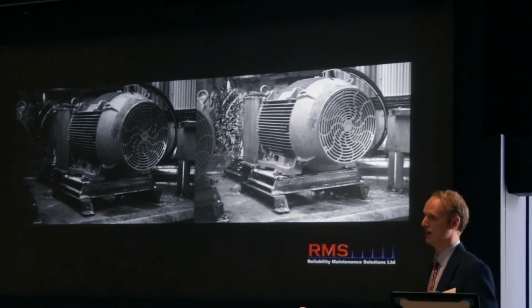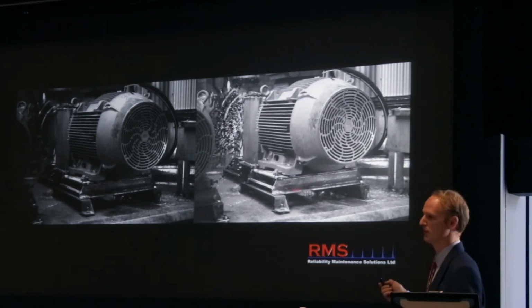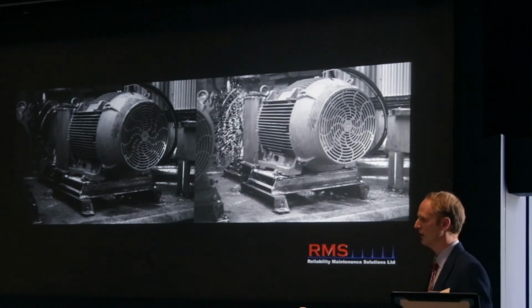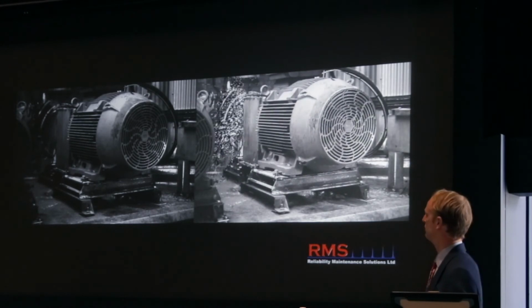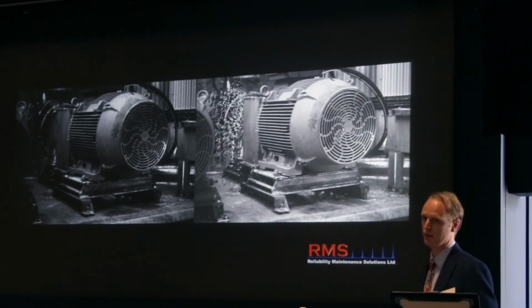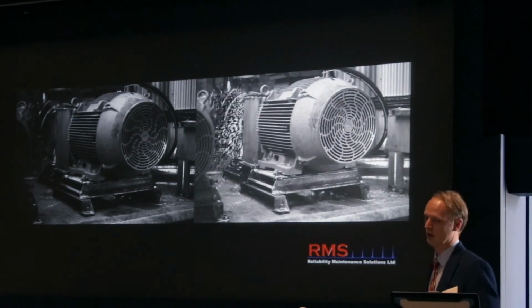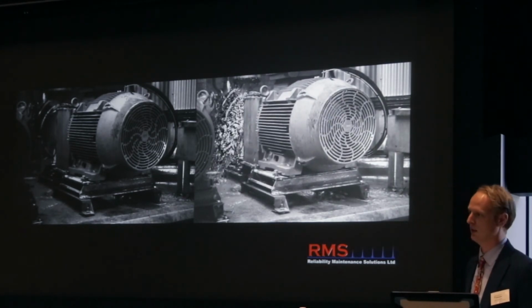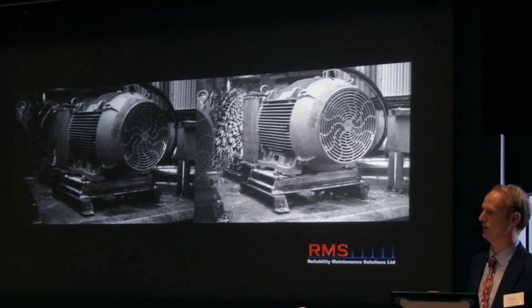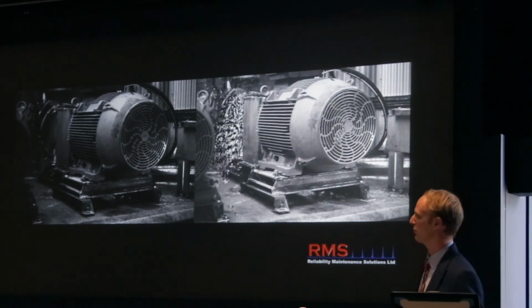Why is that seal failure there? It's pretty obvious, because this machine is allowed to move this amount in operation. So we also found very quickly, in 6 weeks, we had bearing defects on these machines. So at this stage, using this technology early on during the commissioning phase, we can avoid problems in the future.